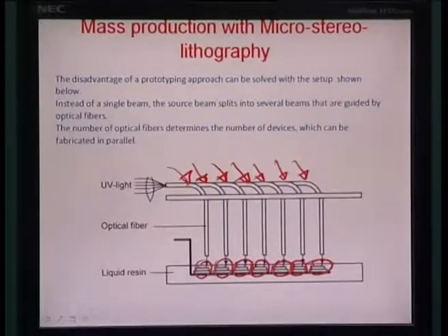This can be translated to stereolithography, and that way very fine three dimensional features can be resolved at a very fast rate because of this digital micromirror device. So, various intelligent processing techniques have been used to modify the microstereolithography process so that you can develop a lot of interesting microscale features on the surface.